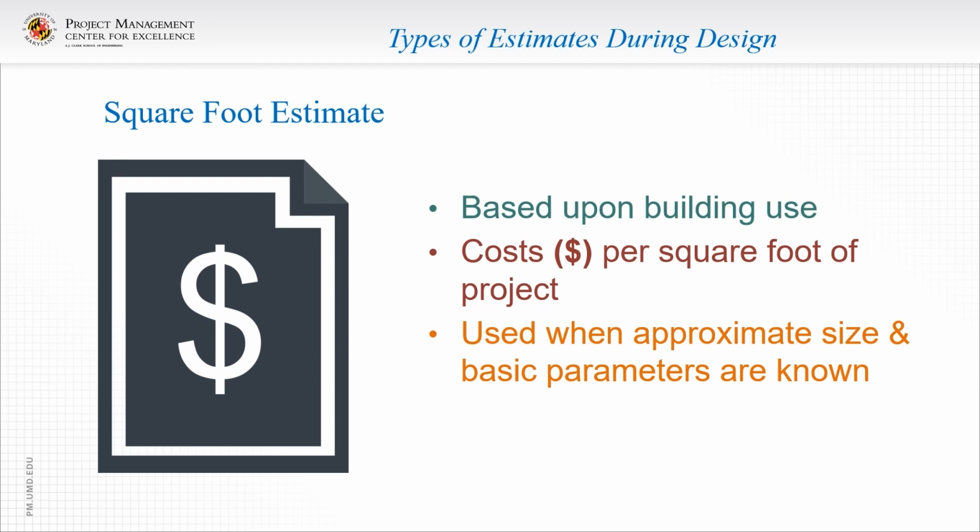Information regarding structural systems, building height, exterior closure, and overall footprint of the building are all factors that will be assumed by the estimator. If real data are not available, a square foot or cubic foot estimate, while more complete than a ROM estimate, is still quite schematic in detail. It is, however, easy to prepare, taking only a couple of hours. The general assumption for accuracy is plus or minus 15%, better than the ROM estimate because it is based on more project-specific information.